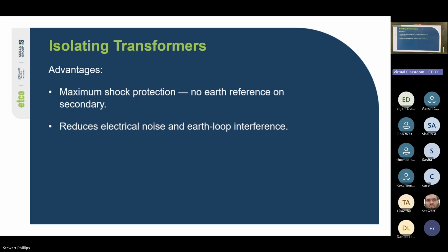Have you had any buzzing on the ground loop, which causes a little bit of noise and feedback? So what you can do is you can use a box called a ground lift box, which basically does the same thing, uses a transformer to separate the signal from ground, meaning that you don't get that noise. It's really common on live audio gear that they use isolating transformers, not for electrical, but for signal.